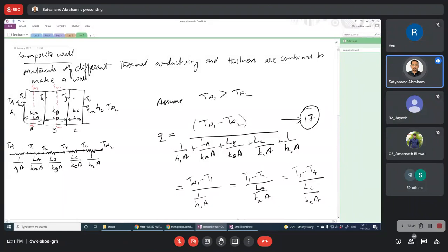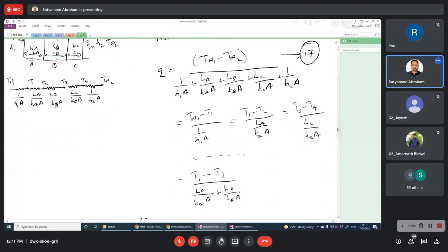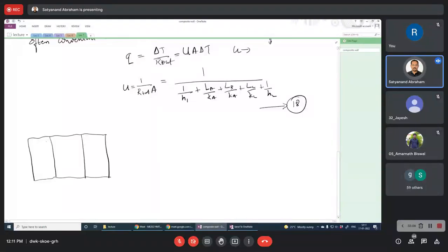Perpendicular to the x direction the temperature is constant because heat flux is in the x direction only, and heat flux is always normal to the isotherm. An isotherm is the imaginary line connecting locations of constant temperature. Therefore, the isotherms will be perpendicular to the x direction in these cases.